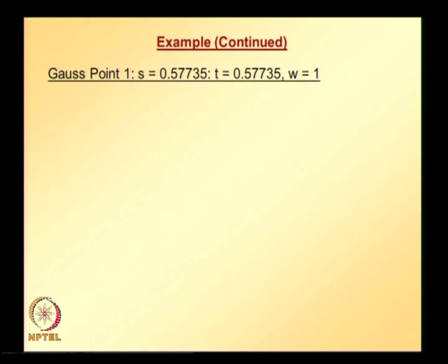Here we are adopting 2 by 2 integration, so in total there are going to be 4 integration points. How to obtain the coordinates and weights of the integration points we already discussed several times earlier. Now let us take one integration point and see the details; a similar procedure can be repeated at the other integration points. The selected Gauss point, its coordinates and weights are given.